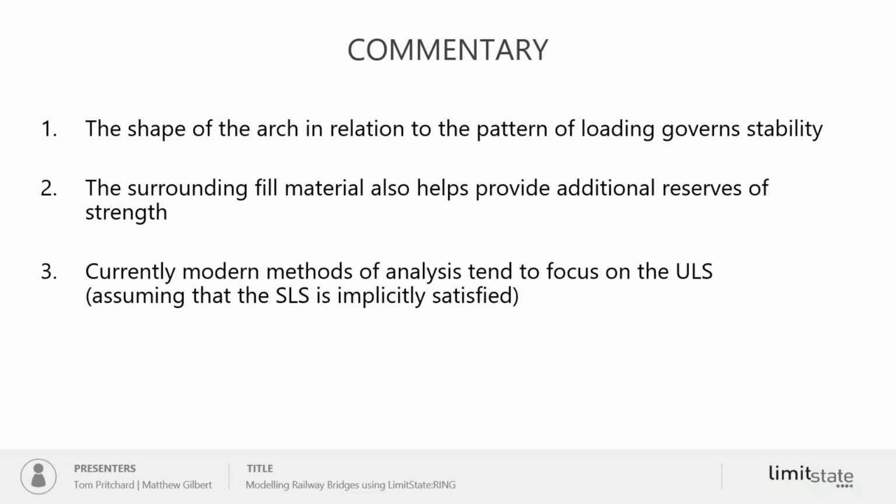The other thing to say is that modern methods of analysis tend to focus on the ultimate limit state, and they assume that the serviceability limit state is implicitly satisfied. That's something that's the subject of active research, and hopefully we will be able to have a slightly more refined approach to dealing with this in the near future.